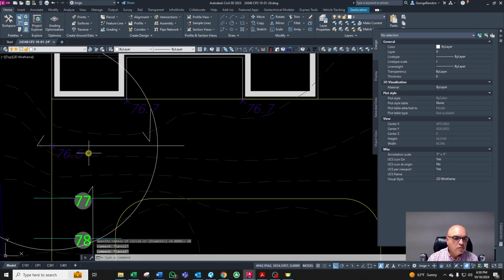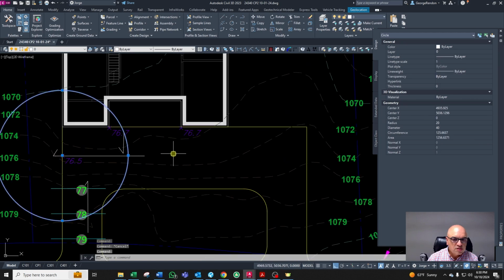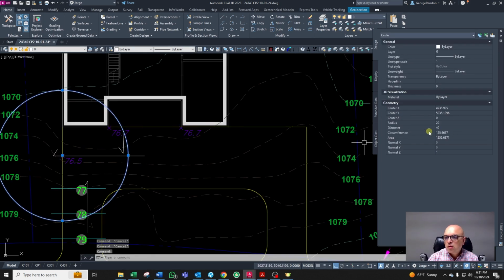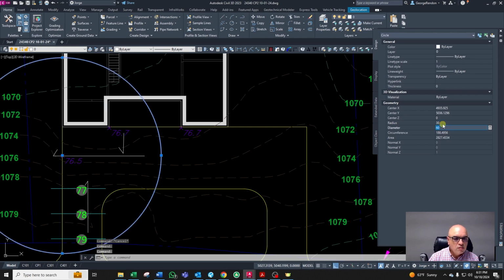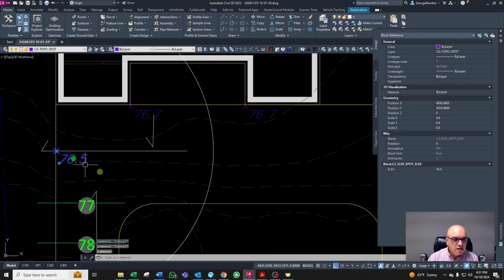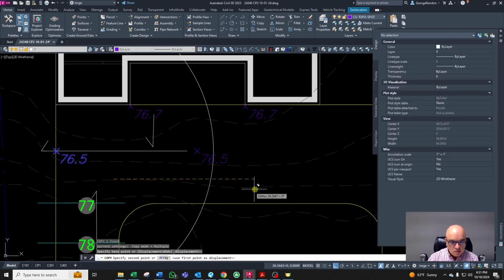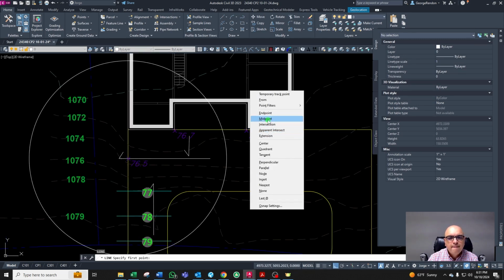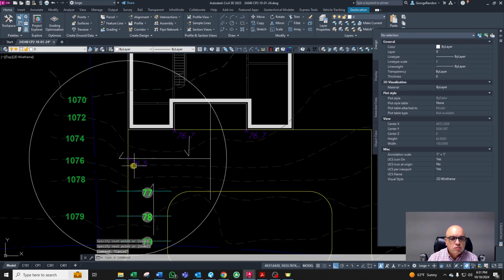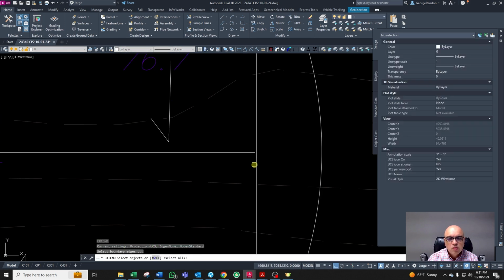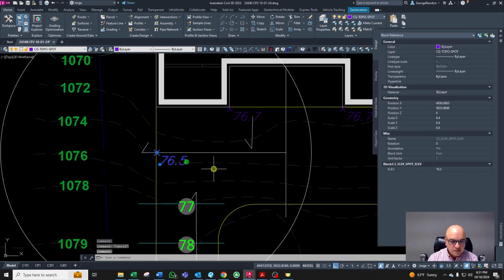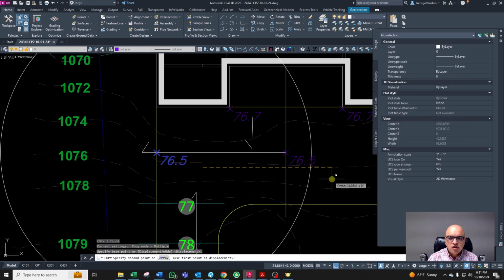Even more, because I need to drain like this from the center of the house. So let's do 30. That is perfect. What is that distance right there? This is 27. I want to drain this at 1%.